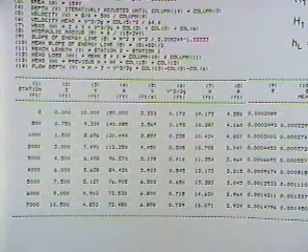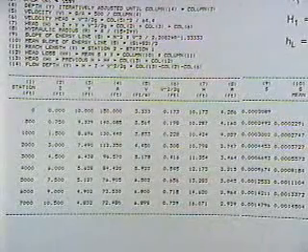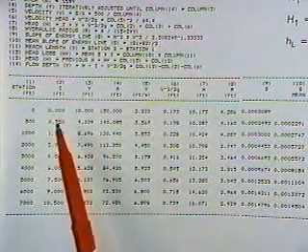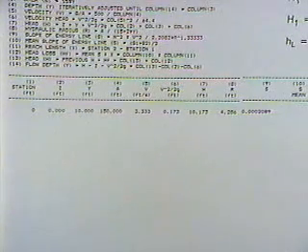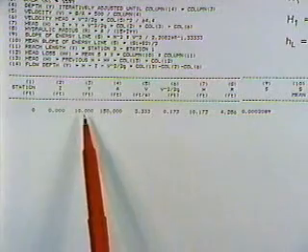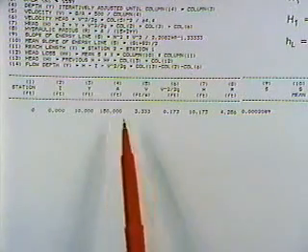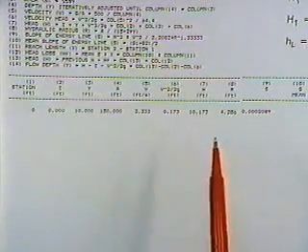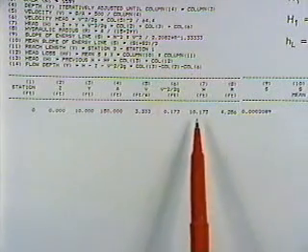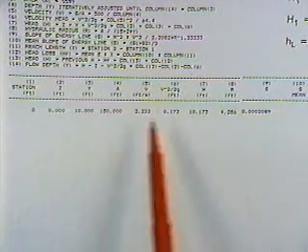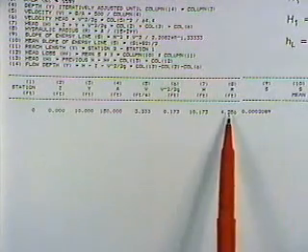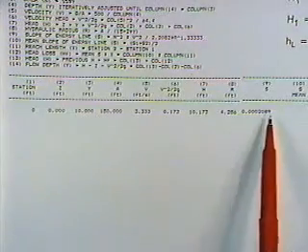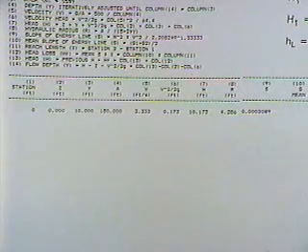And I don't think I'll take a whole lot of time on this simply because we've got so many things we need to cover tonight. But basically what we're doing is, in the first line of the computations, we're given the depth of 10 feet, and given that, once you know the depth, you can compute everything. You can compute the area, the velocity head, and then the velocity head plus the depth plus elevation head, the total head. And then you can compute the hydraulic radius, and you can compute the slope from Manning's equation.